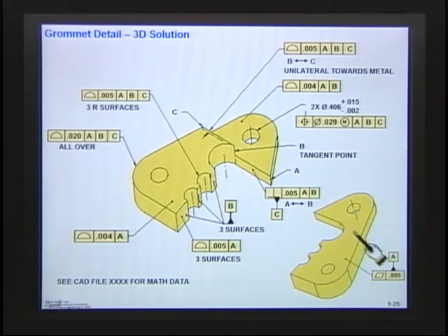You see that face over there? I called off, that says datum A, it's flat within 5. The 3 surfaces here, I called that off as datum B, and I had a profile there. That was the one we had. And this was the perpendicularity. Remember that face? We said perpendicular. And once we had that, then we located that surface. We said it had to be on that line or down 5 thousandths. And then this surface here, remember that flat surface there? You see I just ended in a dot. That's profiled within 4 thousandths.